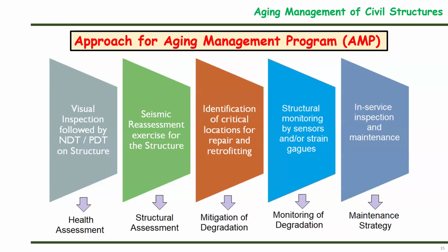Many of the facilities which were constructed, say, 50 or 60 years ago, using the seismic criteria available at that time, may not satisfy the current seismic criteria. So we can carry out this seismic reassessment exercise to find out where we have got the deficiency as far as the structure is concerned.